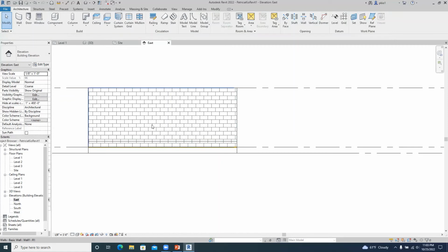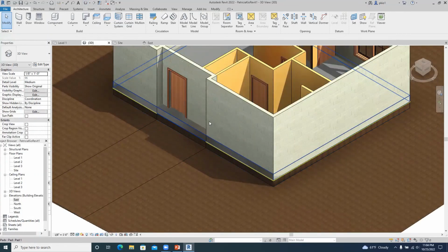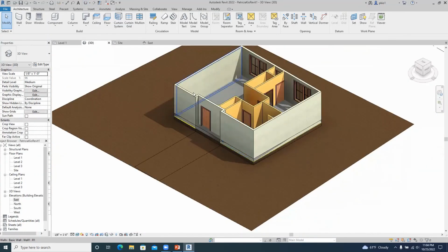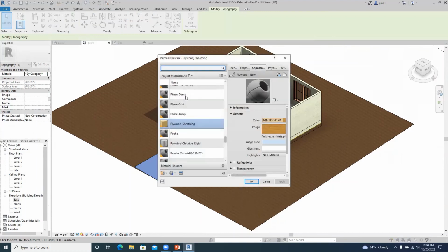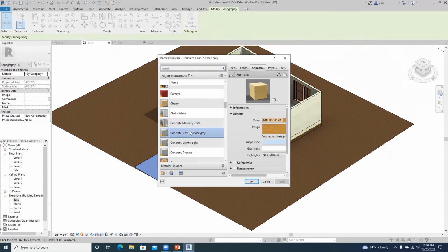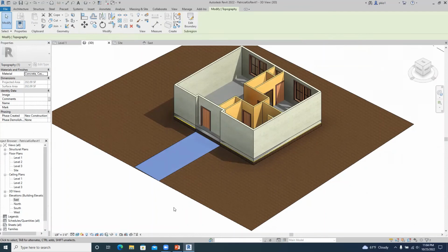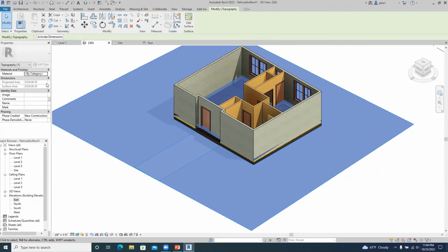So we set the height of things by checking the numbers. So click here. Now we see that we have the building pad and then the building, and then we have the site. So we can change the material, select on this material, and then come to this space beside this, click, and then we can change that to concrete cast in place. And then select this material, and to make it grass, and then come to material.